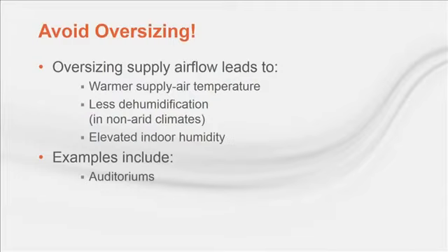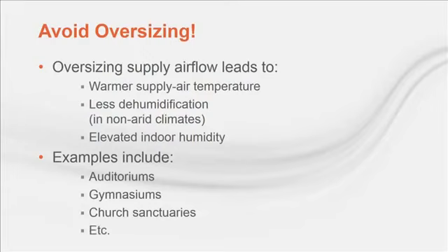The unit is not technically oversized, considering those few times when full occupancy occurs. However, it performs like it's oversized for the vast majority of operating hours. Gymnasiums and church sanctuaries are other similar examples. Basically, consider hot gas reheat for any space with extreme variable occupancy. Please note that the example presented earlier is for comparison purposes only. The resulting space RH level for any particular application depends on the combination of sensible and latent loads in the space and the concurrent outdoor condition.